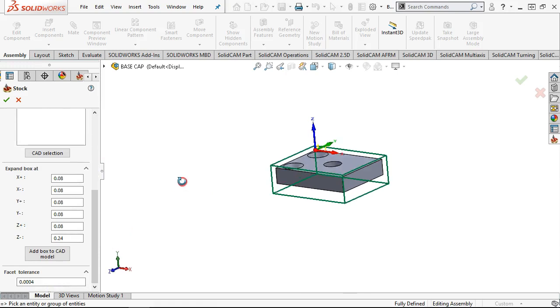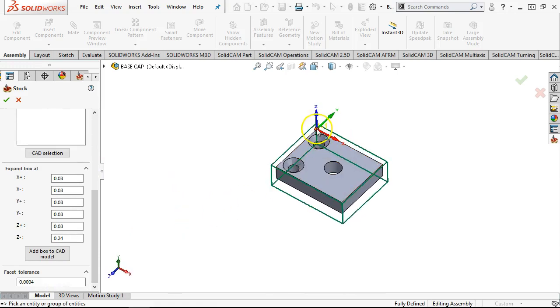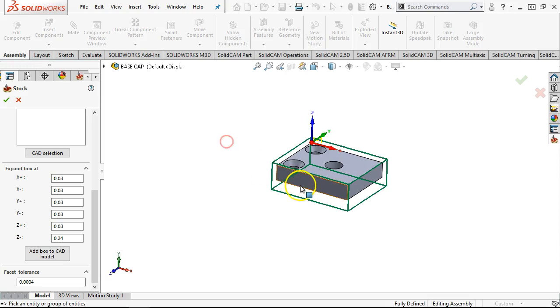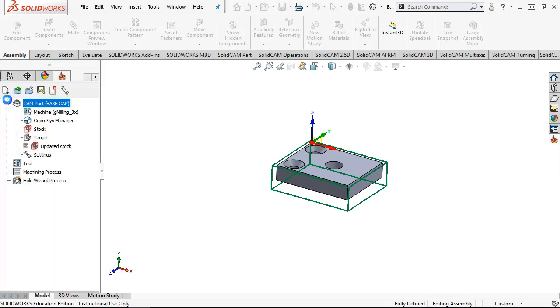All right, so the only one that we set is the 0, 0. The only one that really kind of annoys me is the Z, because I like to see my Z depths from position and set it at the control to go a little deeper. So the Z plus, I would go with a 0, and then we can go ahead and accept.